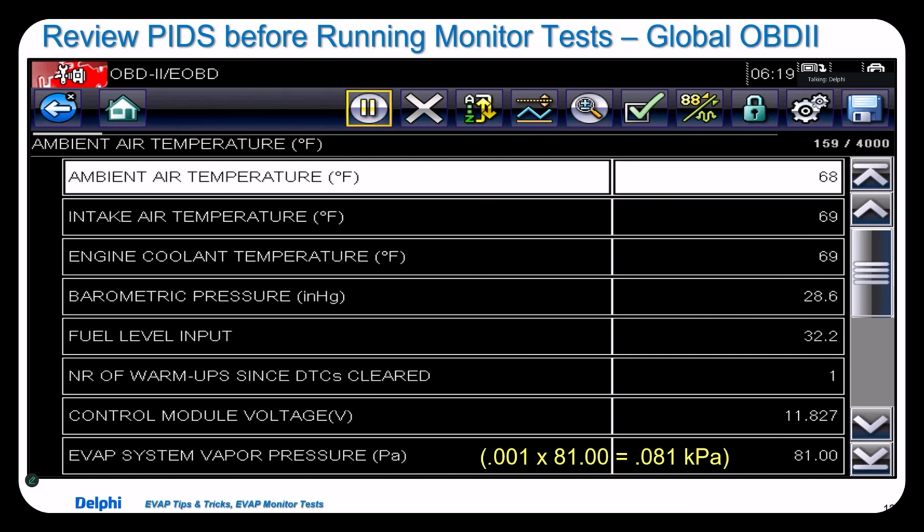Now I also know this is a CAN car because it has fuel level. And if you have fuel level, then you definitely are on a CAN car. Prior to CAN, with most cars, you either had to go into the OE side to find the fuel level, maybe in the body control module, or you looked at the dash and hoped that the gauge was right. So it's important that we get an accurate read on that, and we'll show that as we